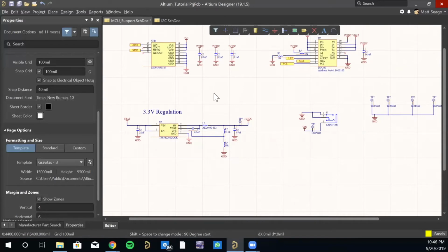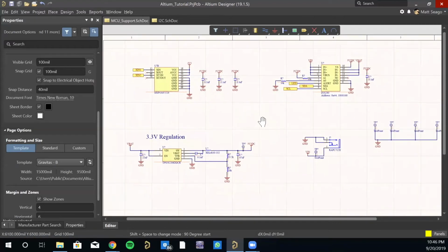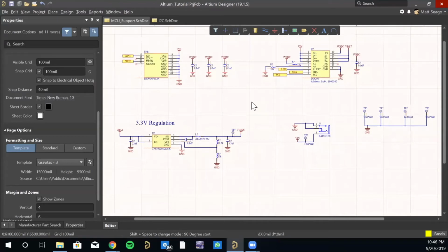And then they'll usually have some bigger capacitors that go around the chip to further help decouple. So be sure you just check that. Just look at your reference design, whatever chip you're using. I'm sure you have a development board for it. Find the schematic for it, figure out what parts they use, and go off of that. It's very important that you look at your reference design. Okay, do we have anything else we need to add?